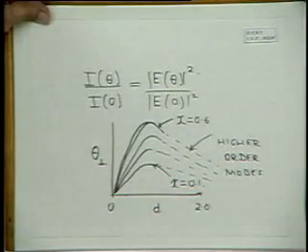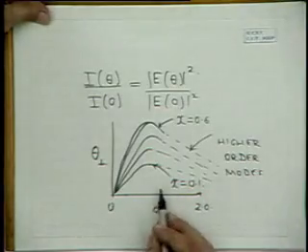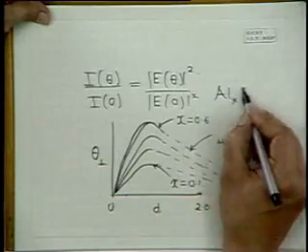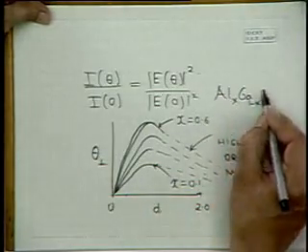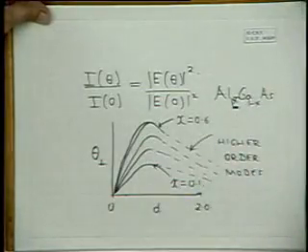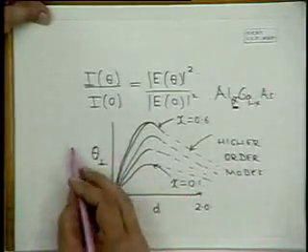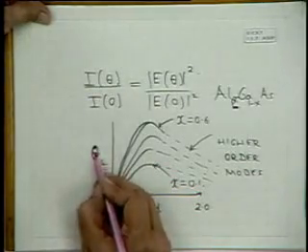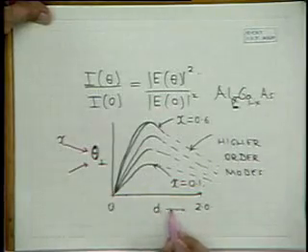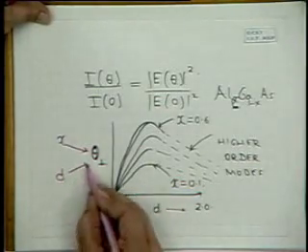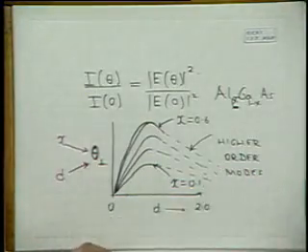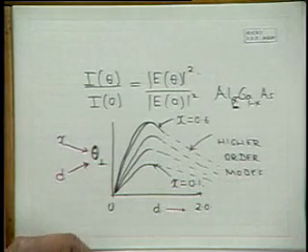Again, this is for an AlGaAs structure, aluminium x gallium 1 minus x arsenide, where the two important parameters determining theta parallel and theta perpendicular are obviously x and the width of the active layer. So I'll continue with this discussion next lecture.